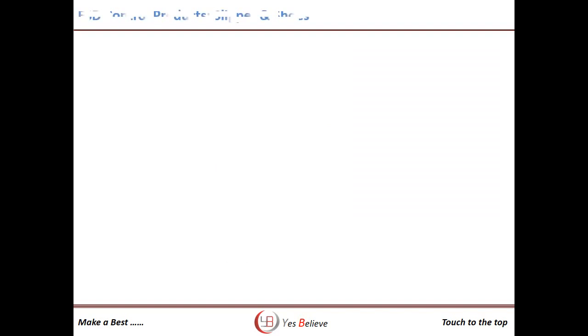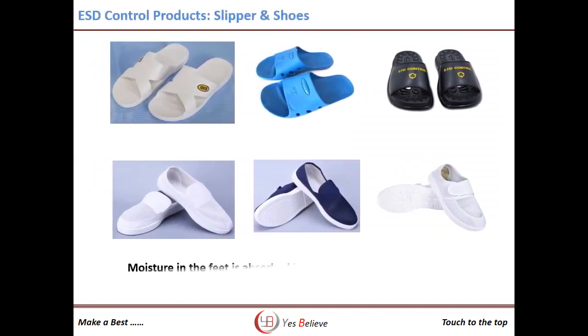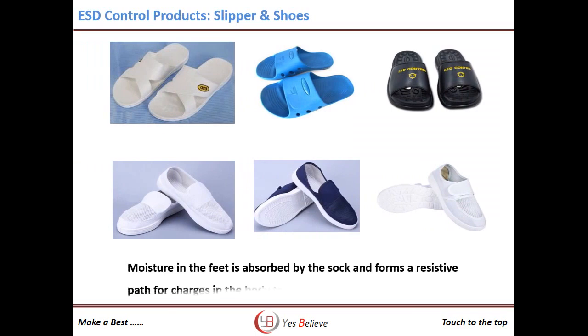Separate ESD slippers or shoes are used on the SMT shop floor. The moisture in our feet is absorbed by the socks. It forms a resistive path for charge in the body to move to the sole of the shoes.